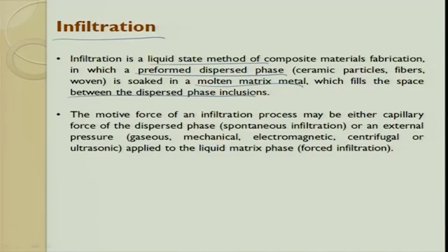The motivating force of the infiltration process may be either the capillary force of the dispersion phase or an external pressure, which is what I told you. It can be gaseous, mechanical, electromagnetic, centrifugal, or ultrasonic. The liquid phase is forced inside during infiltration. If it is by capillary action or vacuum, it is called spontaneous infiltration. If it is pushed intentionally, it is called forced infiltration.